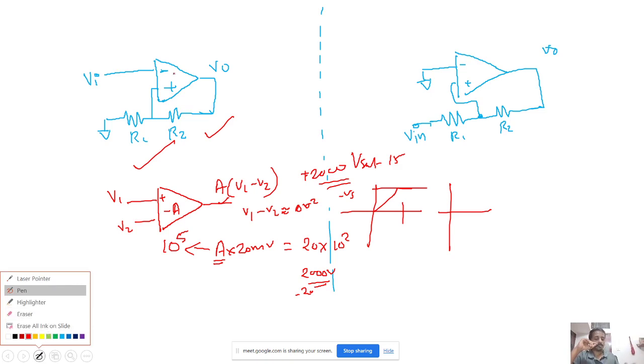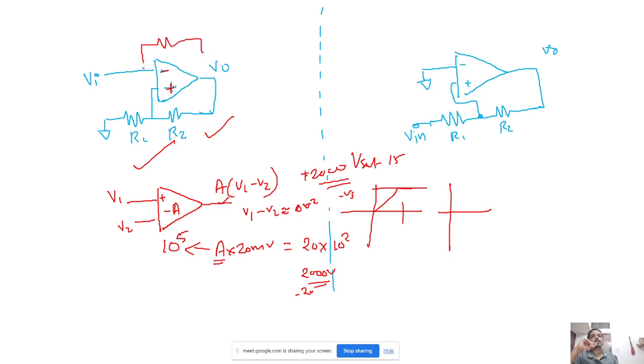No, this is like, just check to which node we have connected. This minus and plus, right? Only when I connect a feedback to the inverting node will our virtual ground concept work, or the feedback method will work. Otherwise, if it is non-inverting, we cannot assume that. This is actually similar to our positive feedback, right? So it will add on, and the output voltage will rise up. In negative feedback, the output will slowly reduce, and it will go to a stable state.